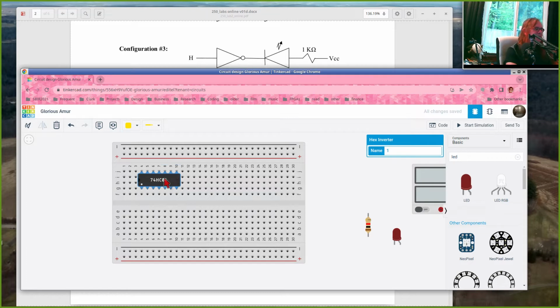And so if you put this chip right here, you're connecting pins to each other that you didn't necessarily intend to connect. And if I put it down here, exactly the same thing happens. And there's only one way you can put this chip on this board where that doesn't happen, and that's to go across this middle section. So if I put this, say, right here, I've got 5 connection points for this bottom pin, which is called ground.